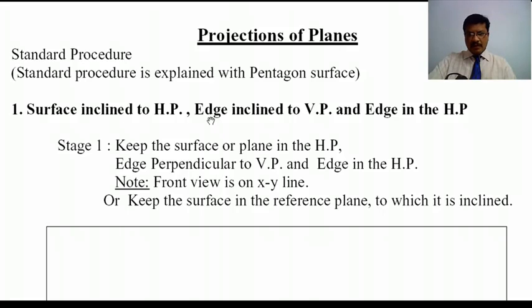So while solving the planes problems, you have to identify the surface inclination and edge inclination with respect to the reference planes. So here in this case, surface is inclined to HP. So you have to keep the surface parallel to HP. So always we have to keep the surface parallel to the reference plane to which it is inclined. In this case, it is inclined to HP. So make it parallel to HP.